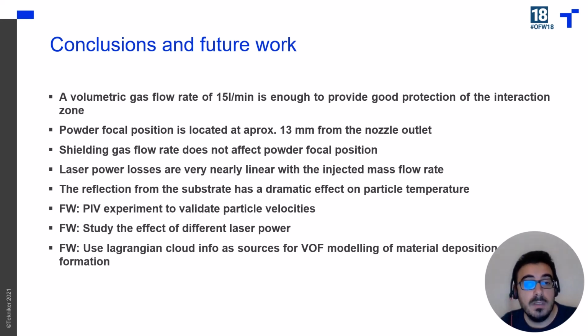We have also seen that the shielding gas flow rate does not have a big effect on the powder focal position. Also, that laser power losses are very closely linear with the injected mass flow rate. And also that the reflection from the substrate has a great effect on particle temperature. So it must be considered when dealing with this problem.